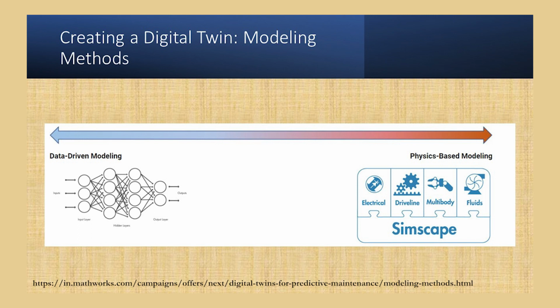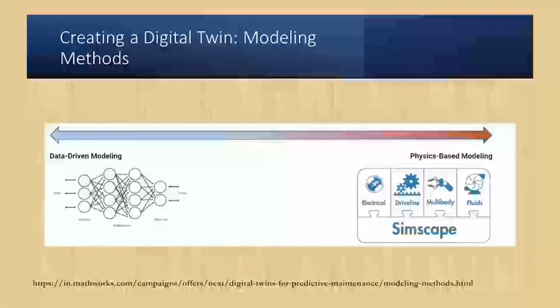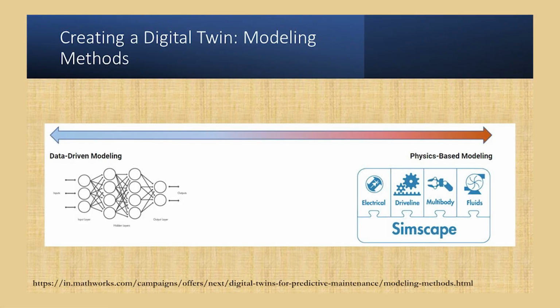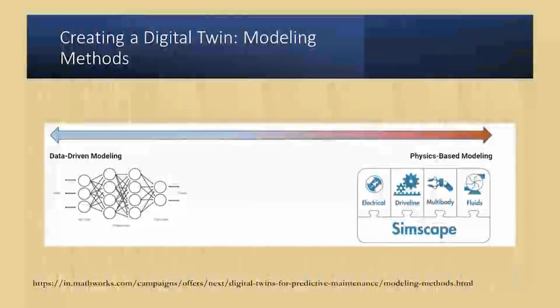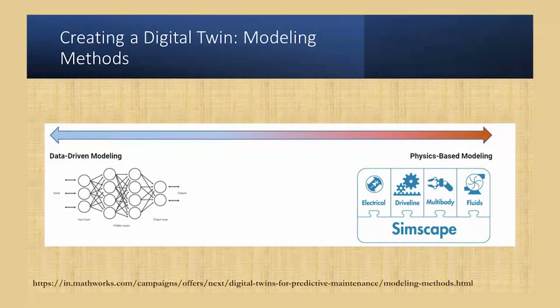Once you model the temperature distribution in the workpiece, then you can tell that this much zone of the workpiece will be above the melting point. So, that will be removed. Based on that you can find out what is the material removal, and based on the pulse width, you can find out the rate at which the material is getting removed. So, that is physics based modeling.